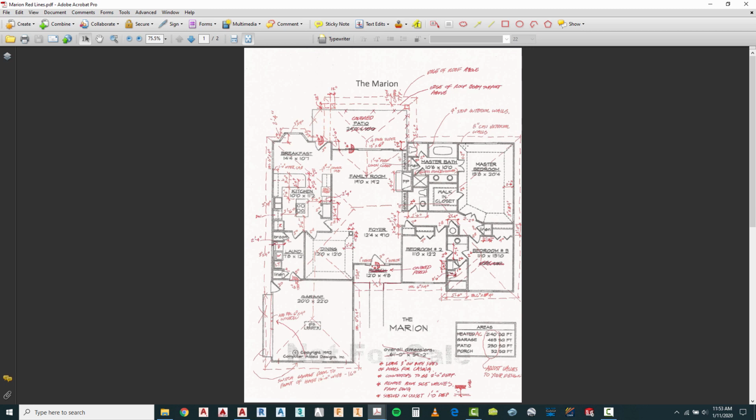Some of the most important modifications is that here in South Florida we use 8-inch CMU, which is concrete block, for the exteriors of the construction. In this case, you can see that the exterior walls are about the same width as the interiors. We will be using 8-inch CMU for the exteriors and typically 4-inch stud interior walls. I've also included a number of other modifications that we will be applying, including a different roof layout, which then